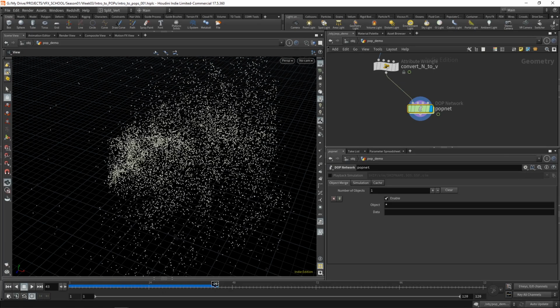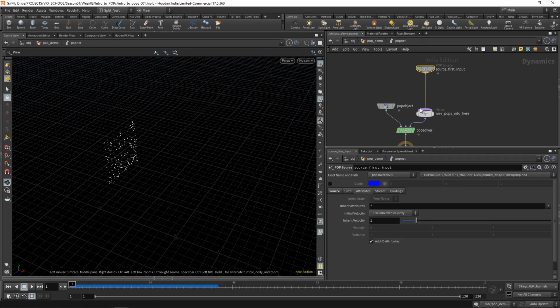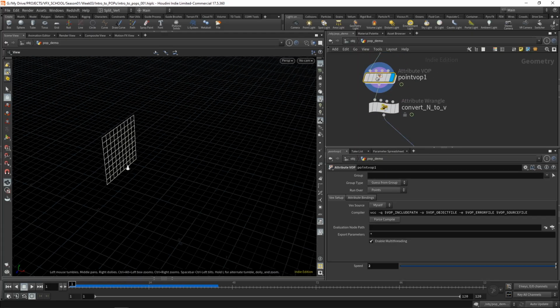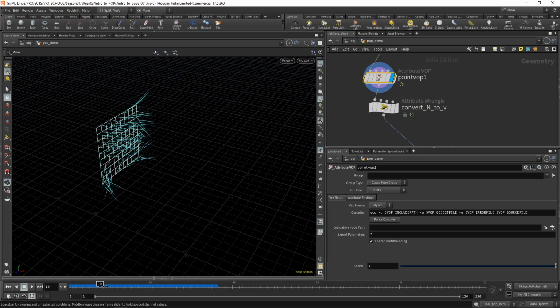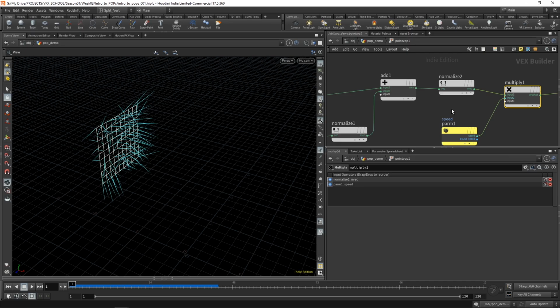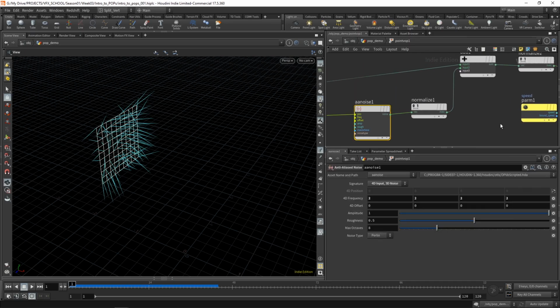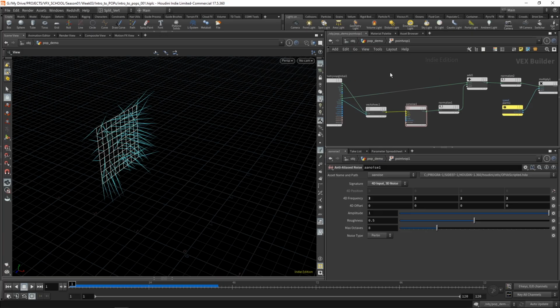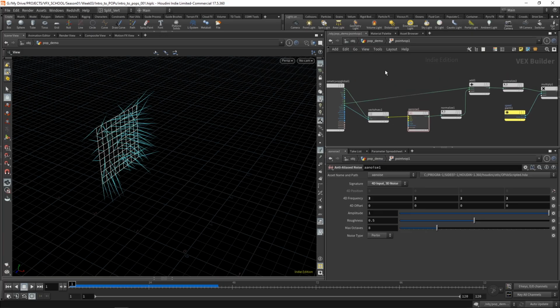And there's a pattern to them that we can't really see, but if we go here, the type of variation that's happening on the normals is this. It's going to be changing through time. The speed at which it changes is affected by the frequency, of course, of the anti-aliased noise. We can expose these parameters, but right now they're all being exported. All the particles are having all these different directions, but they have pretty much the same speed. What we can do is create a different noise to give them different speeds as well.